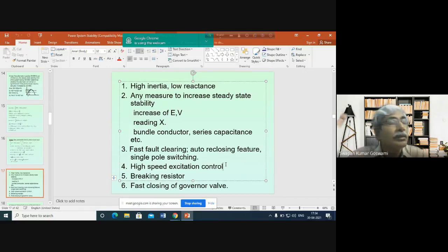And already I mentioned to you that the terminal voltage of the generators is generally kept constant. So how is it kept constant? It is kept constant by the action of the excitation controller. The purpose of the excitation controller is to change the field current of the generator. These excitation controllers will vary the field current of the generator, and by varying the field current, they will increase or decrease the value of E in an attempt to maintain the constant terminal voltage.